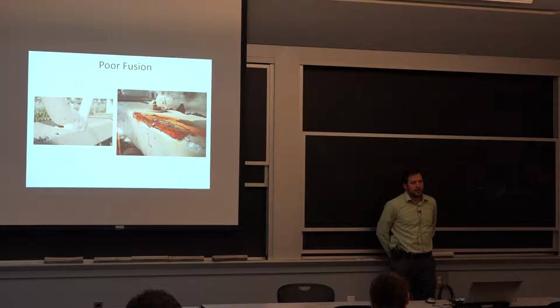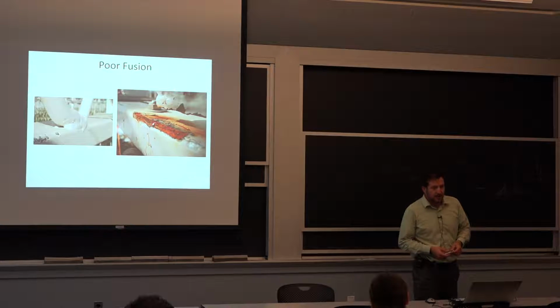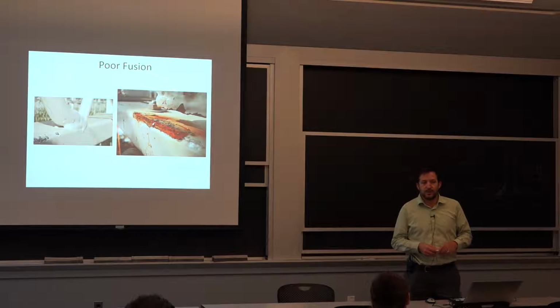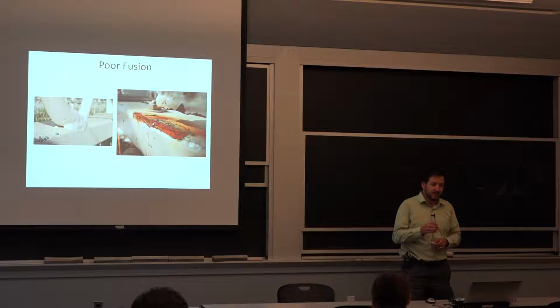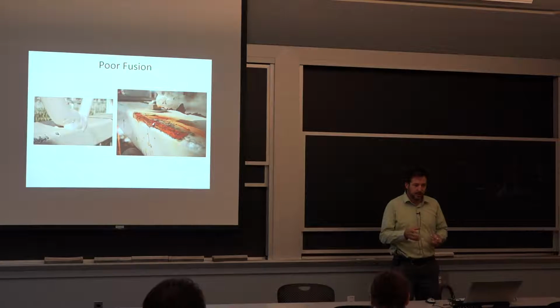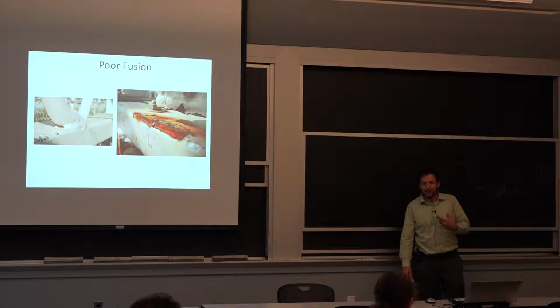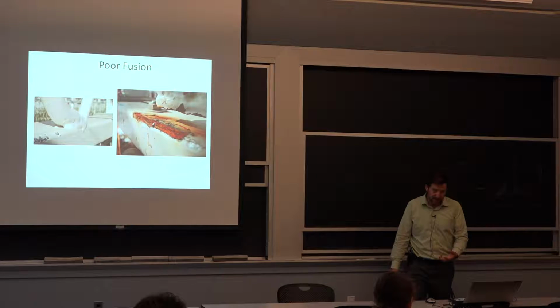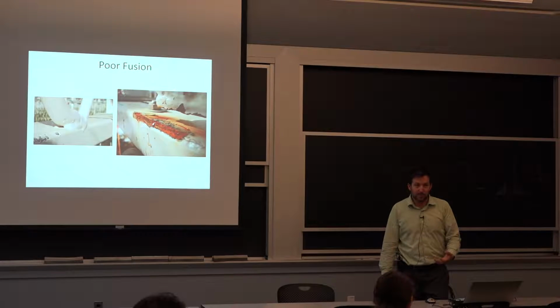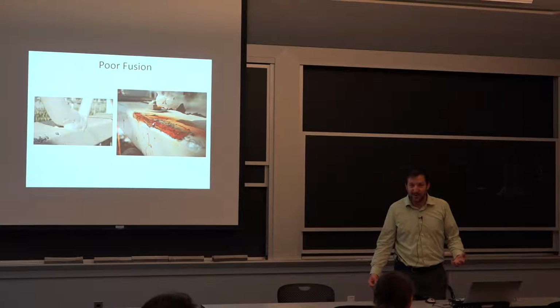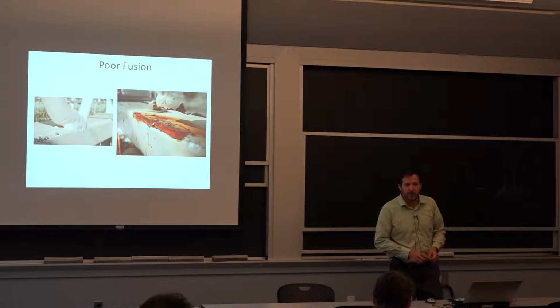judge the fusion. One thing that you'll find a little difficult if you end up having to deal with welding contractors is that in American codes and standards, in AWS, they don't specify that angle. It's a judgment. I have to say, as the welding inspector, there is a problem with your fusion, or it's fine. It's a very qualitative judgment.